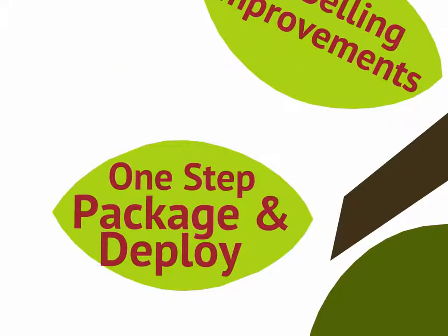One-step package to deploy. Now I can take a ShipConstructor project if I need to, and I can say package it up. What we will do is zip up the database backup, grab all the project files and all the folder structure for that project, and put the whole thing into one file as a package. And on the other end, when you need to deploy it, there's a command in ShipCon that says deploy a project, and you point at that file, and we'll rebuild everything you need to be able to start working in the new project right away.